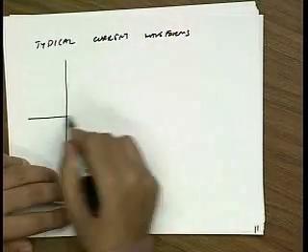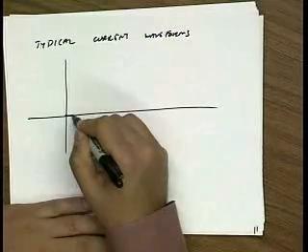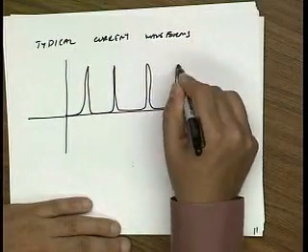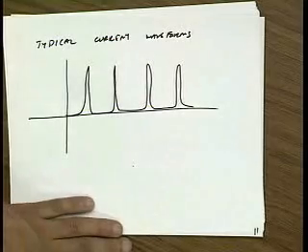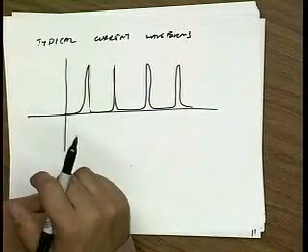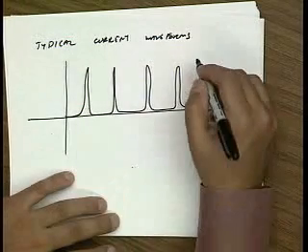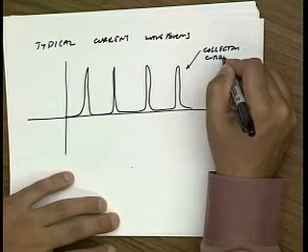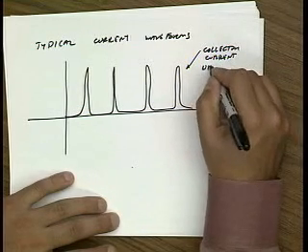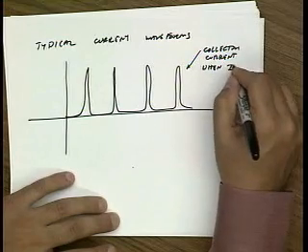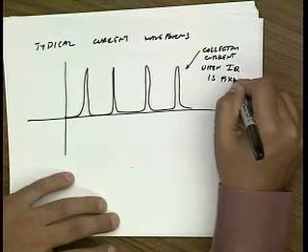As I mentioned before, the current waveform, or the way that you inject energy into the tank, doesn't have to be continuous. You can actually inject current into your tank in a bursty manner. So this is the collector current when IQ is fixed.